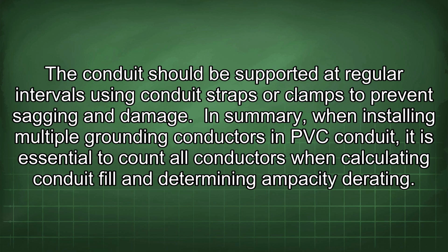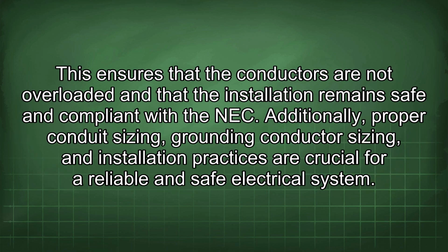In summary, when installing multiple grounding conductors in PVC conduit, it is essential to count all conductors when calculating conduit fill and determining ampacity derating. This ensures that the conductors are not overloaded and that the installation remains safe and compliant with the NEC. Additionally, proper conduit sizing, grounding conductor sizing, and installation practices are crucial for a reliable and safe electrical system.